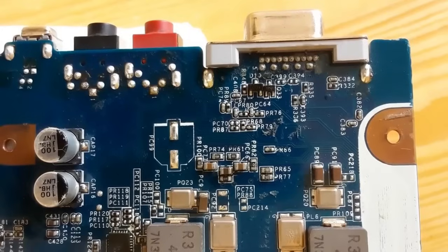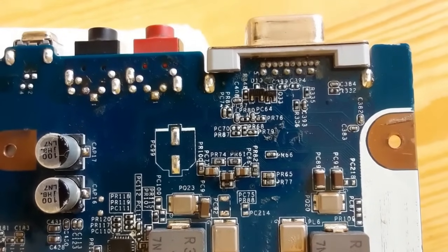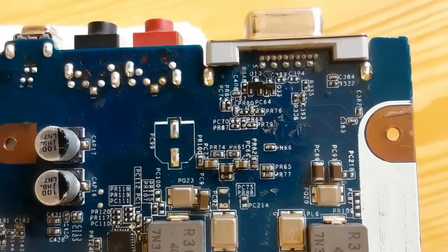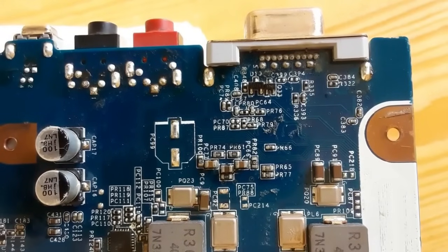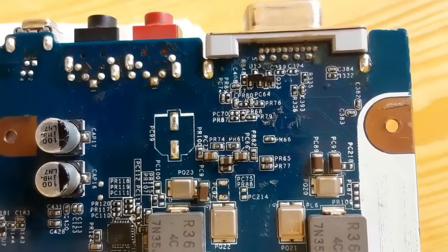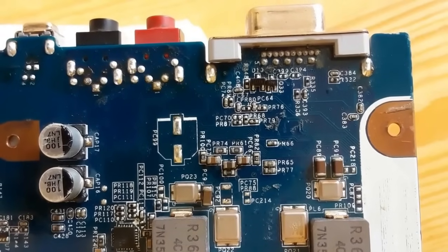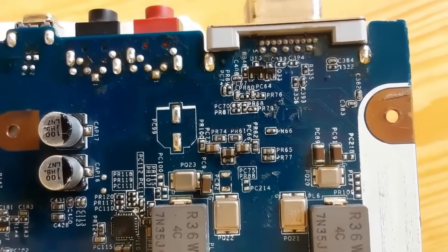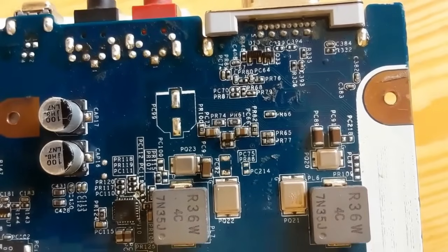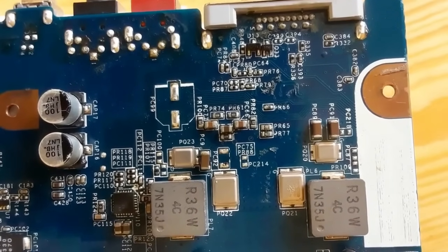Okay, these connectors or ports can be a USB connector, can be the VGA connector, can be a connector for the touchpad or for the keyboard, for the screen, etc. That's why you should check the soldering state in your motherboard, especially for the ports and connectors. This is also one of the common faults that you can encounter